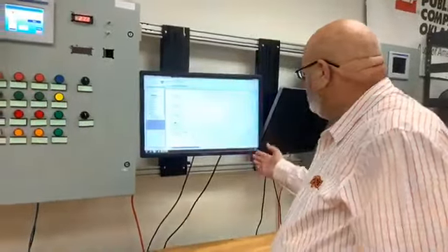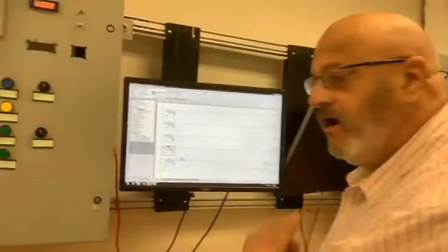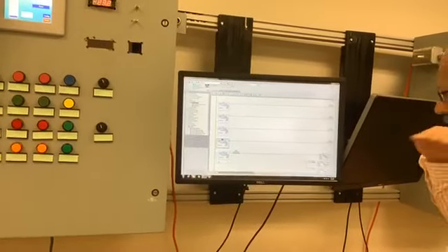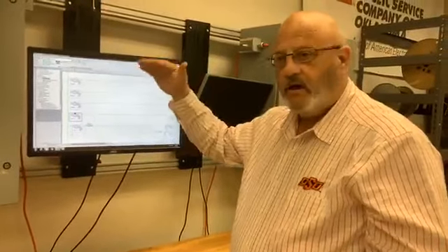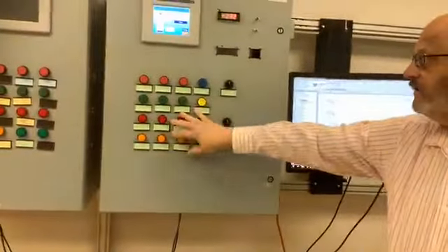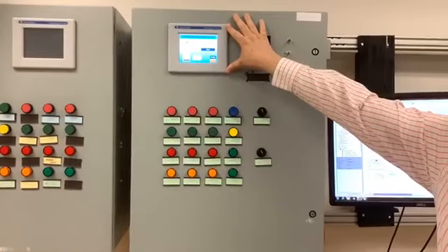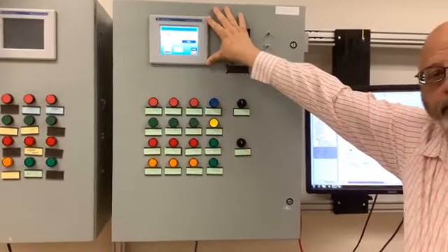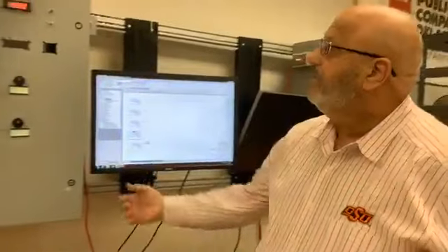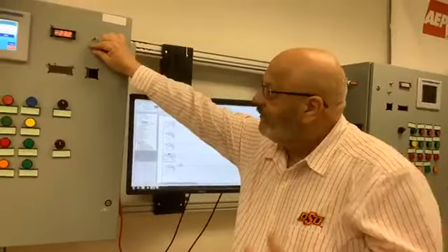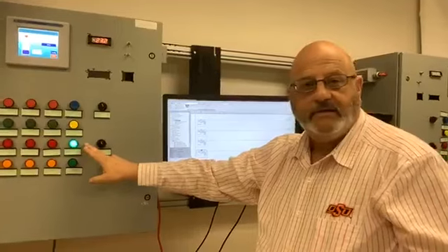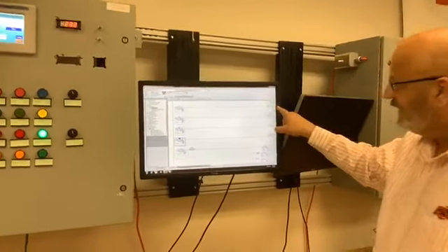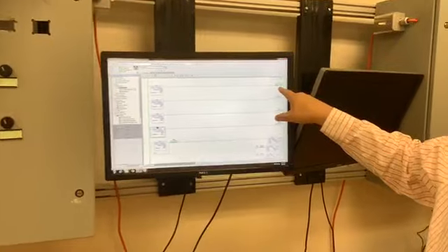Here is a program one of my students wrote just last semester. In it, all he was supposed to do was monitor pressure, and as it got to certain levels, trigger certain alarms. We have manual lights that turn on, and then we have virtual lights that turn on up here and give us an alarm if we reach a certain threshold at a certain point in time. For example, as I increase this dial here, simulating pressure increasing, here's a pressure level increase. At the same time, in the actual program, I see that level increase also.